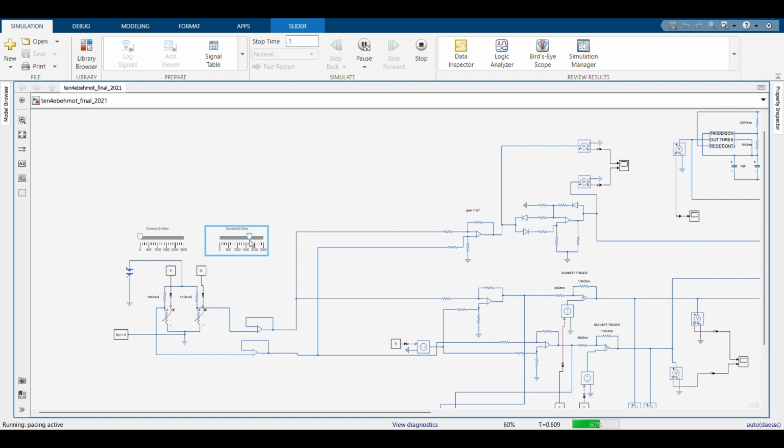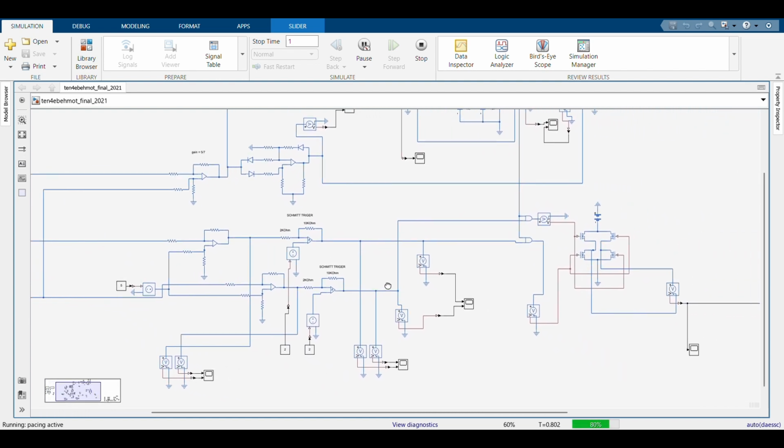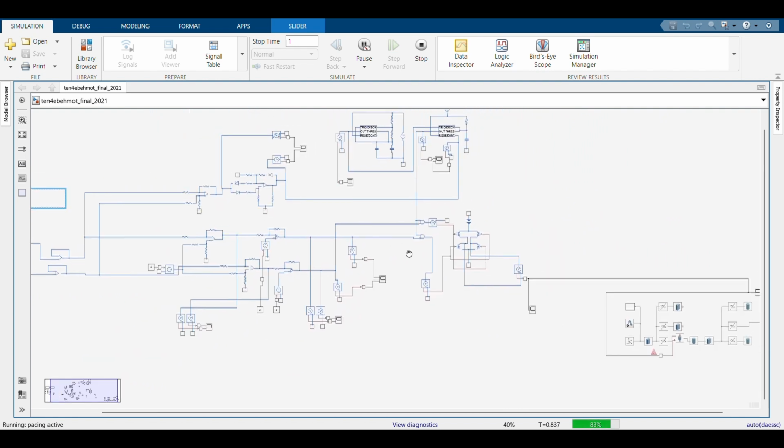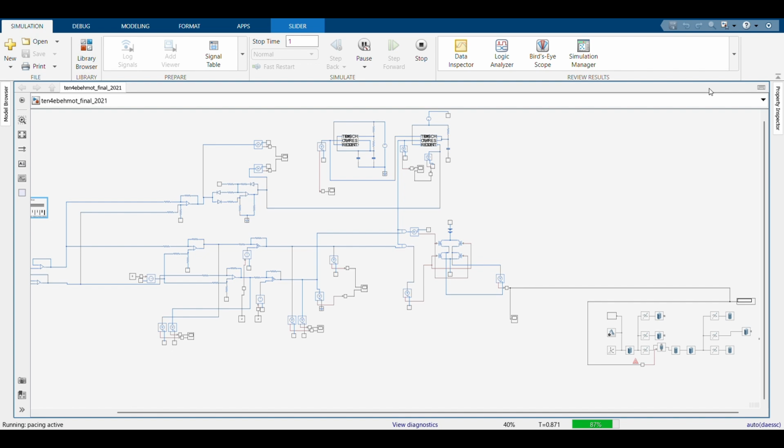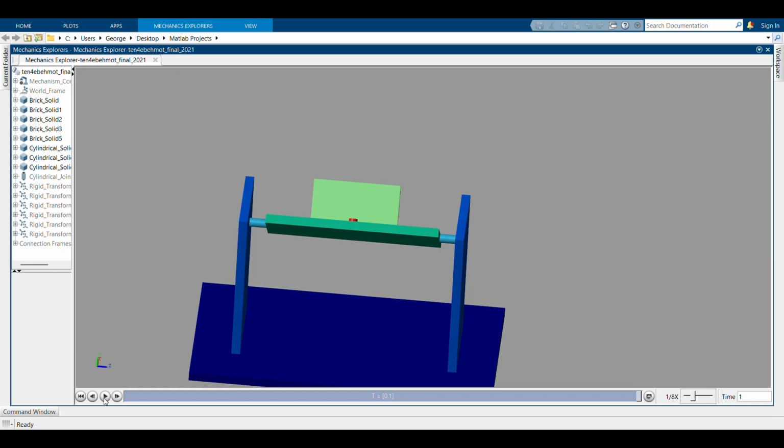We're gonna pass this signal to the PWM port, to the control pin on the second 555 timer. After doing so, we're gonna take the signals that are coming from the voltage divider through two different paths, where we are gonna do some signal conditioning, Schmitt triggers, which is gonna provide us with a dead band to avoid jittery movement or any noise in the lighting. We need the motor to be able to sustain stability when the solar panel is pointed to the sun.